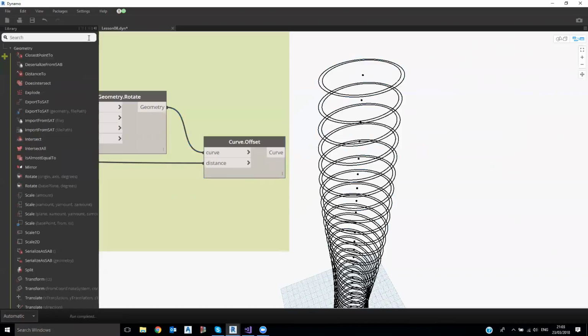To be able to convert a curve into a polycurve or a NURBS curve, you need first of all to create a discretization of the curve. And to discretize, to evaluate, how is called this operation, the curve, you need to create a couple of points around the curve and then interpolate with these new points. How we can do that?